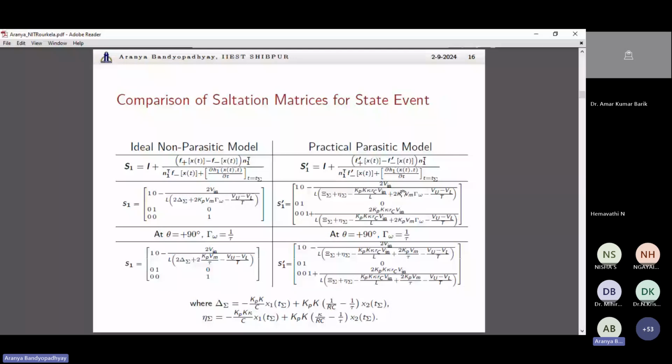We will fixate it at the positive peak. Then it comes down to a case like that of the DC to DC converter. Then, when we multiply all four state transition matrices, it will indicate the stability of a periodic orbit. Then it will make some sense.